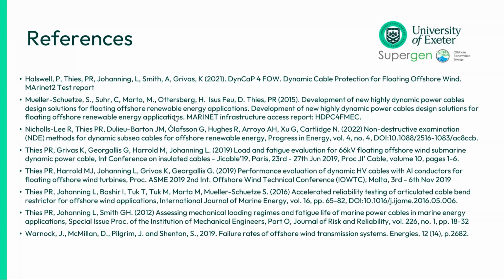Yeah, thank you, Philip. Because it's almost cascading failures, and it's understanding those failure mechanisms. So say the attachment of, for the sake of the argument, the buoyancy module. Parts of your buoyancy modules stay intact but lose attachment, or fall off the cable, or move along the cable to change the shape. That means you now have a different load regime on the cable that it hasn't been designed for. And then that overloads the cable, and so on and so forth. So what's not a straightforward failure could actually be quite a big impact on the cable life itself.